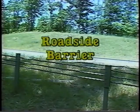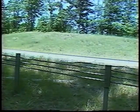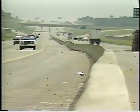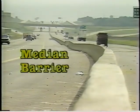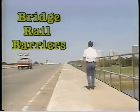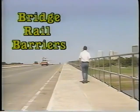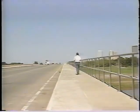In a government manual commonly known as the AASHTO Barrier Guide, definitions of the 3 basic types of traffic barriers are given. A roadside barrier offers protection from one side only and applies to roadside hazards. A median barrier gives protection from both sides and applies to the separation of opposing traffic. Bridge rail barriers provide protection from one side only and are used to keep the vehicle from going off the bridge. They may be used occasionally to protect pedestrians from vehicular traffic.